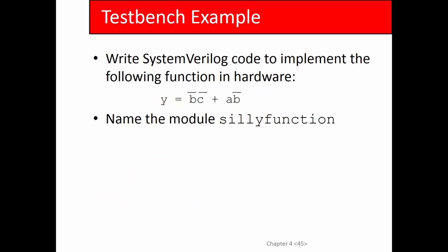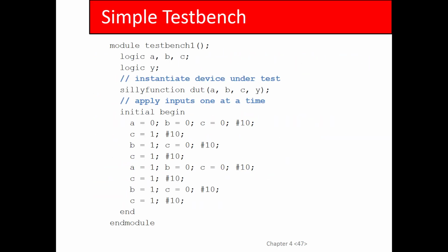And then the last topic was test benches. The idea is that you have a module that doesn't take any inputs or outputs. It's a self-contained module because it creates inputs, sets inputs, and sends those inputs into the design under test, the design that you're testing. Usually it also evaluates the outputs of the design under test and prints an error if there's a mismatch between the actual output and the expected output. Sometimes those are called self-checking test benches.